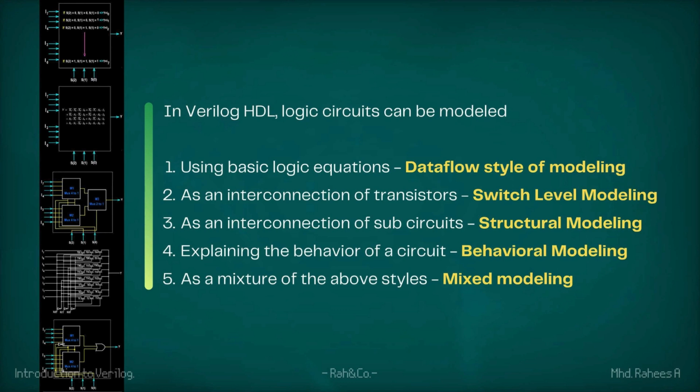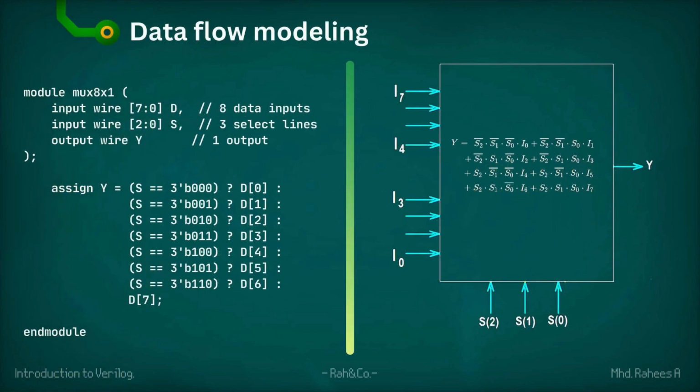If the system is represented as an interconnection of transistors, then the style is switch level modeling. If the system is represented as an interconnection of subcircuits, then the style is called structural modeling. If we model a system by considering the behavior, then the style is behavioral modeling. If the system is modeled as a mixture of the above styles, then it is called mixed modeling.